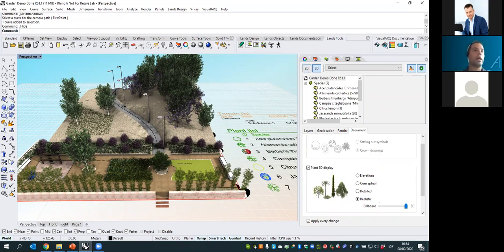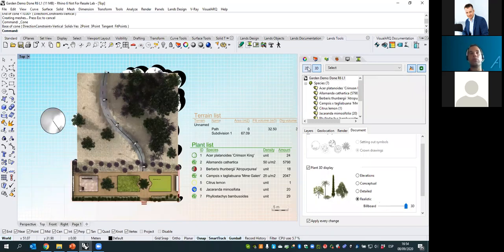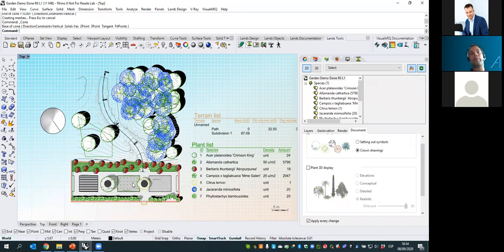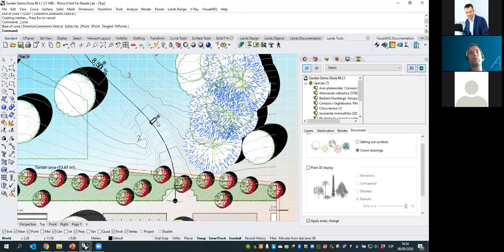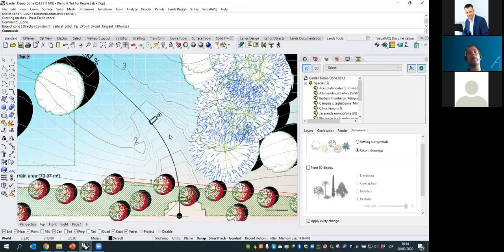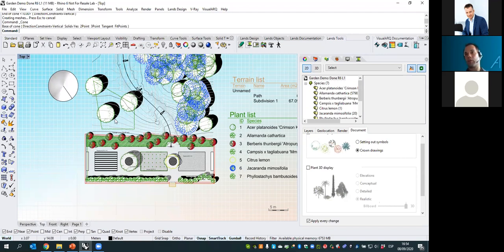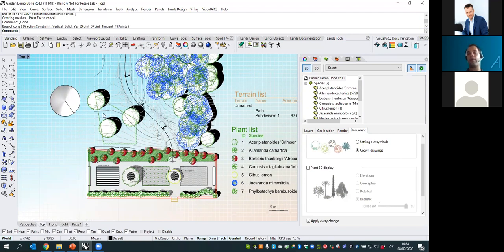So that means that if we work with any geometry like a cone, this cone will be seen as a circle from the top when we switch to the representation. For the lens elements, or the elements from the library, they already have a 2D representation. Same for plants, but for the other elements, or blocks that you can integrate into the block library, the 2D representation will be the projection of the top view.